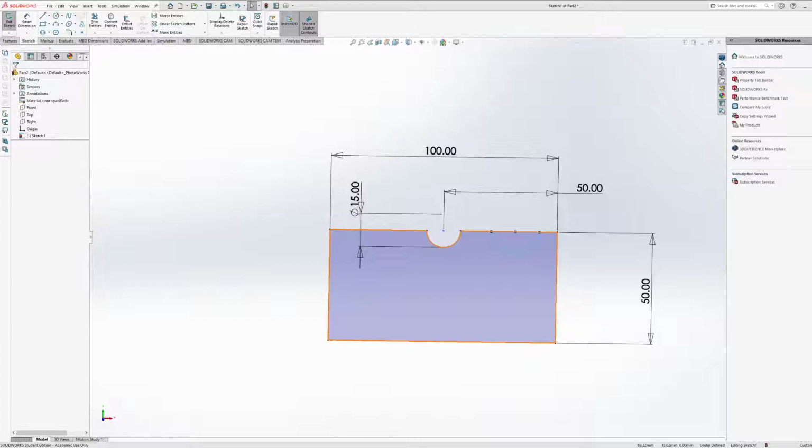So my advice would be to try to make a single sketch plane first, as accurate as it is to whatever it looks from one of those normal views. And then you can play around more with any of the extrusions or extrude cuts, or editing your geometry in any sort of way.